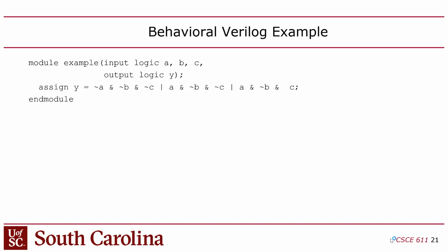You take a Python program and scramble the lines of code, and you've broken it, right? But in Verilog, you can do that because every line of code, or every statement, I should say, runs concurrently, because every one of those statements represents a circuit, and circuits don't have any kind of ordering associated with them. There's no program counter like you have with software because you're making hardware. So there's no place where your code is running at this time. If you open this in a debugger, there's no current instruction pointer in there. It's just everything runs at the same time, right? So generally speaking, you can just scramble the lines of code.